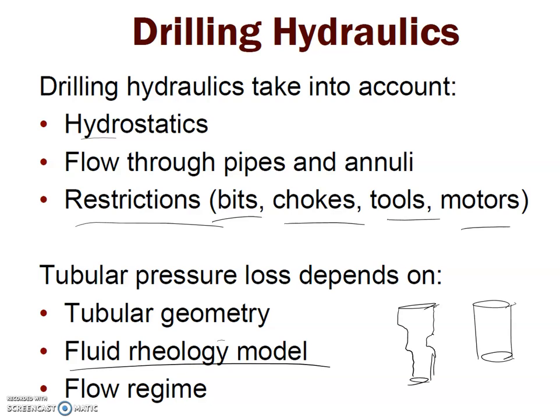The rheology of your fluid: is it a Newtonian fluid, non-Newtonian fluid, Bingham plastic, power law fluid, Herschel-Bulkley model? All these fluids have different pressure losses that we need to consider, and also the flow regime. We have either laminar flow or turbulent. You have probably learned that in your fluid mechanics course, but we will talk about that as well.